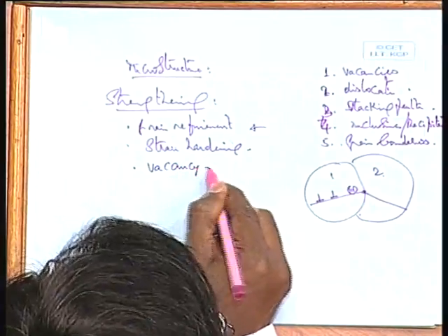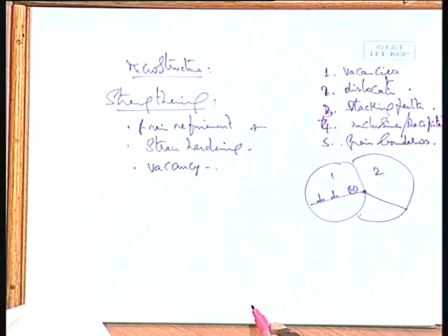What is called vacancy hardening? There is a possibility of what are called quenched-in vacancies, which can act as obstacles. For example, you heat a pure metal to high temperature and cool it rapidly. We all know that the vacancy concentration in a material is always temperature dependent.